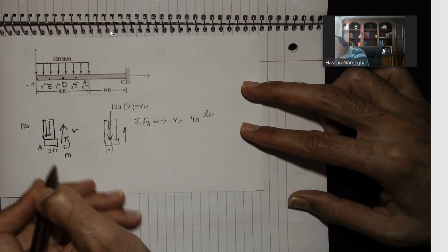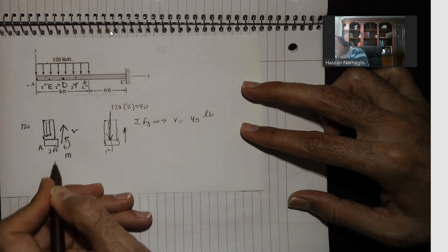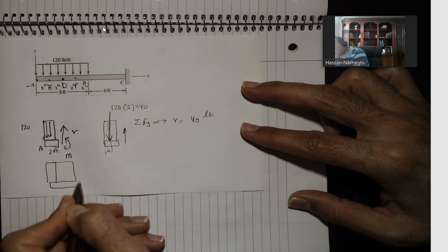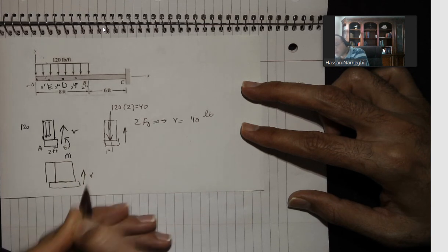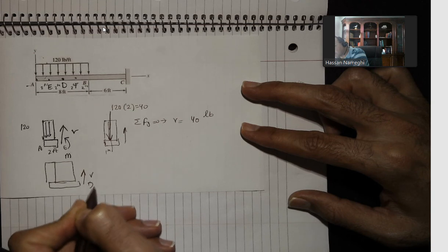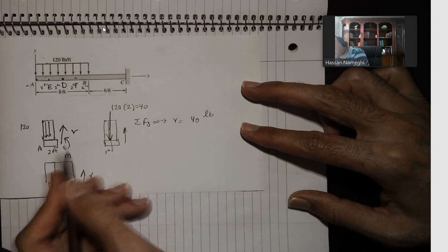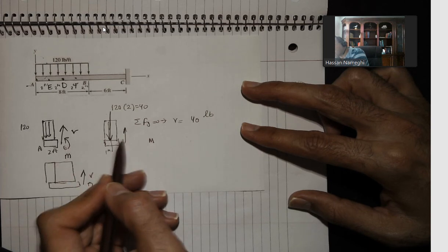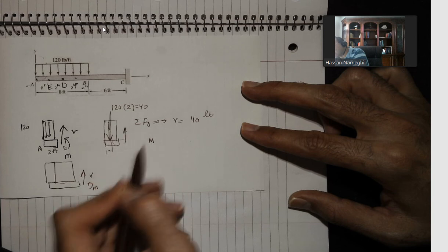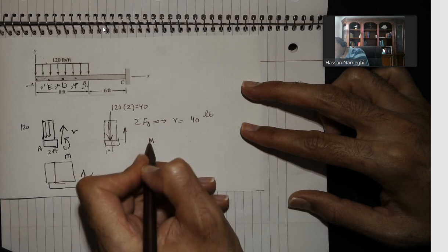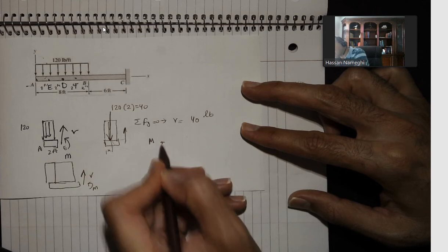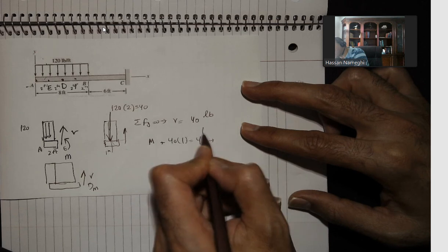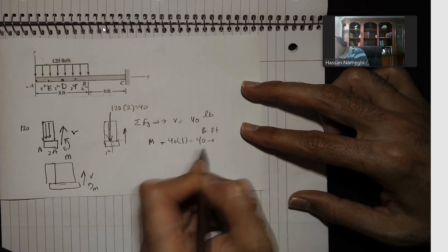Now, this was from point A to point E. If I cut it at point D, so I have a little bit longer, V is like this. Then we have a moment here. In this case, the V was 40 and the moment M. Now I have the 140. Again, this is going to go counterclockwise. So M plus 40 times 1 is equal to 40. So I'm going to get 40 pound-feet on the moment in this case.